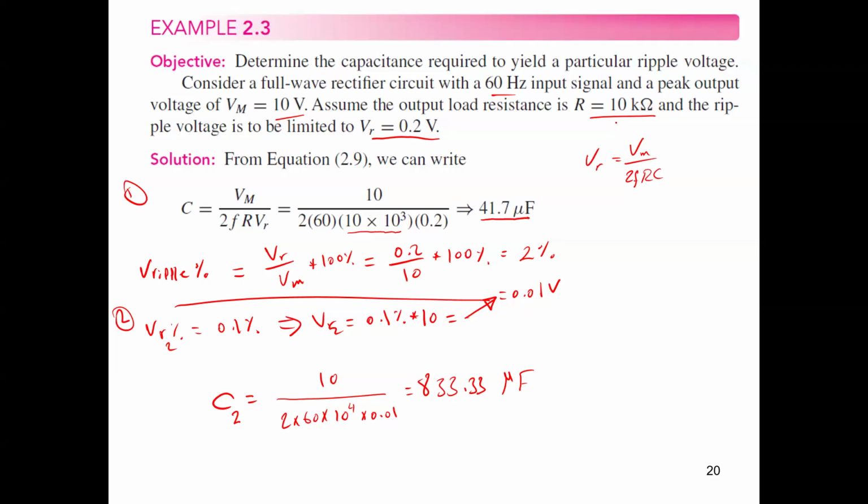We will see this together in our lab. How can we make sizing without knowing the resistance value? In this case, you have to find the equivalent resistance seen by the rectifier circuit. So R here means the circuit resistance seen by the rectifier.